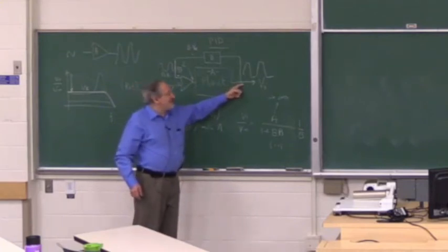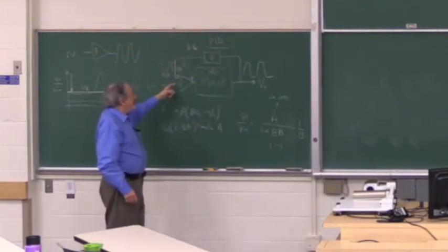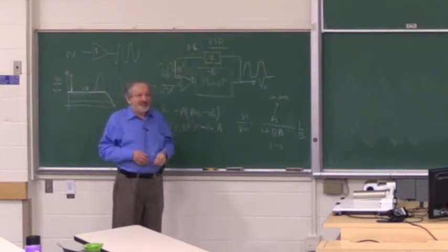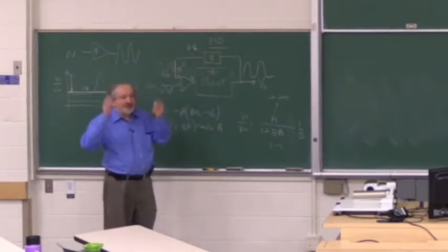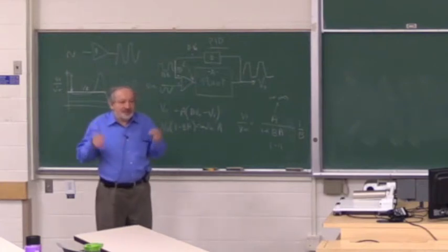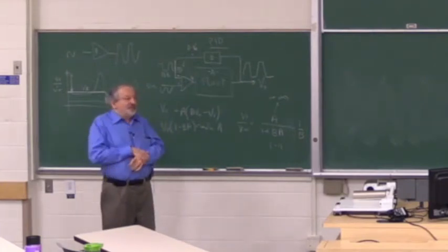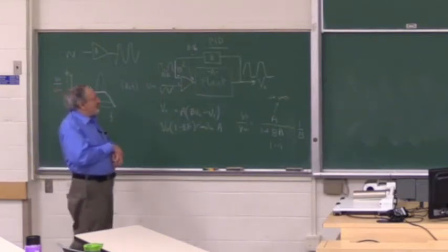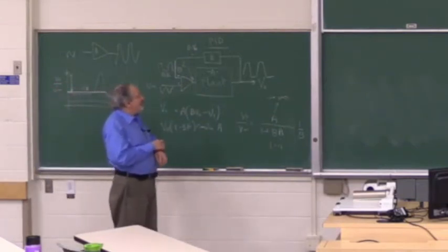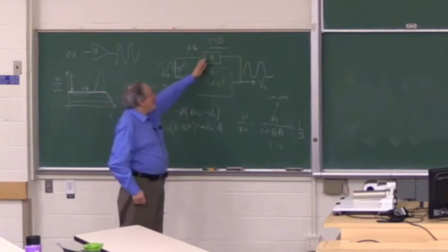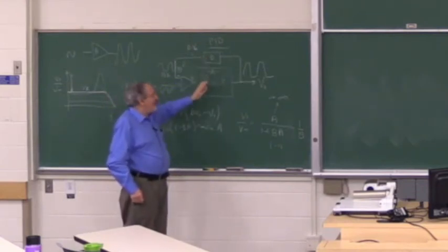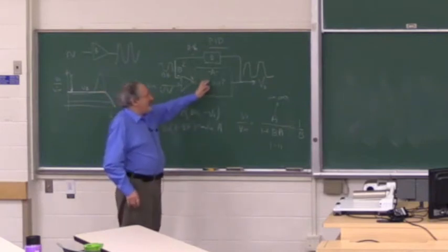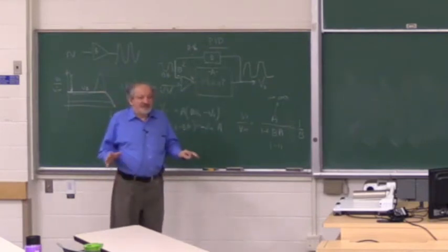But once it becomes bigger, it becomes even bigger, and then adds again and starts growing, basically growing uncontrolled until it saturates or oscillates. Okay? So clearly, there is some relationship between the stability and the amount of phase shift you can tolerate and the amount of gain you can tolerate. Because clearly, if the gain is less than 1, it can never oscillate.